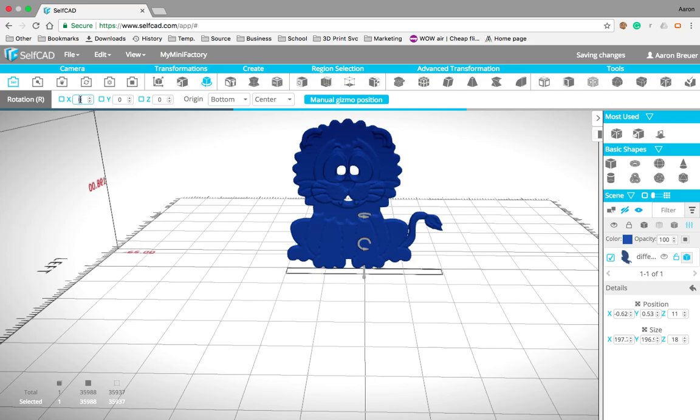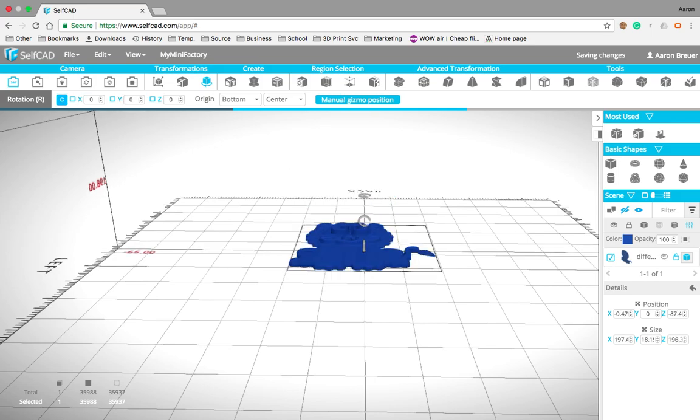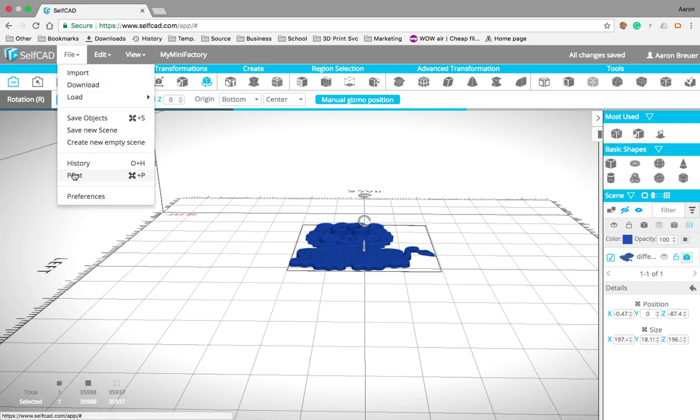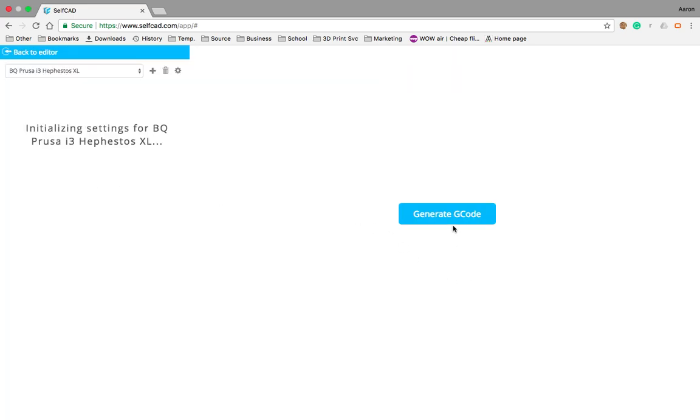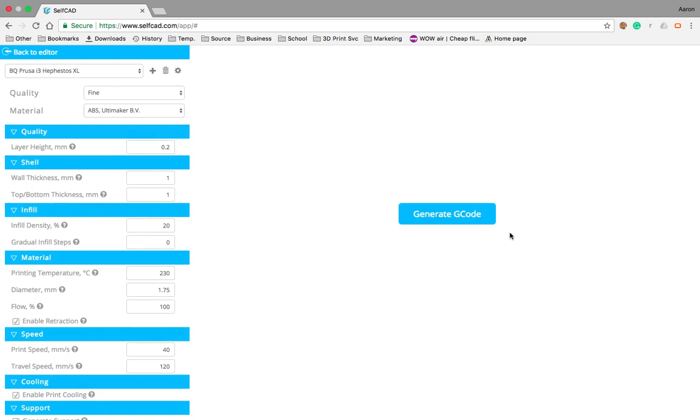I just need to rotate around the X by 90 degrees. So if I flatten it, and then slice it and print, I'll leave the same settings, everything the same. And you're going to see we have only 91 layers, much less. And you see the output, you see why, because it now slices it the same way we imported it, the way it's on the floor. So it will slice the entire thing in large slices rather.